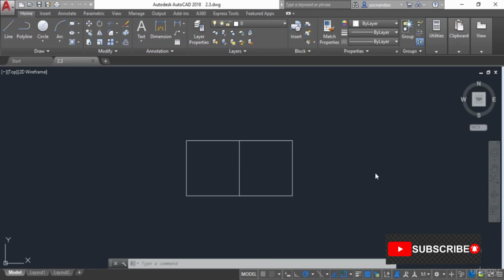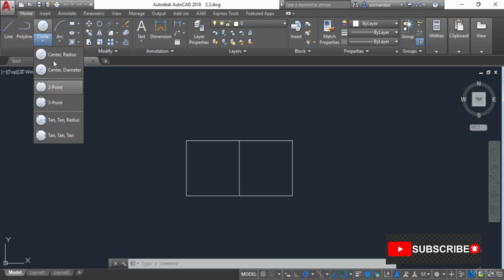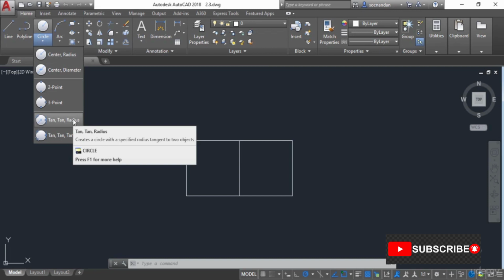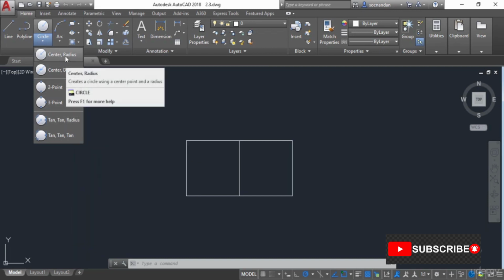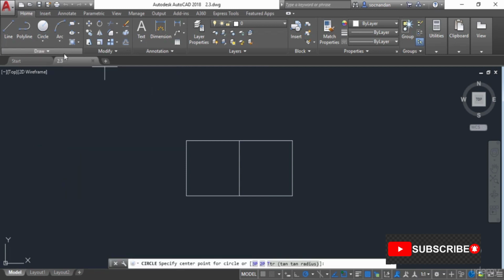In this video, I'll tell you about the circle command of AutoCAD. So you'll find the circle tool here on the Draw panel of the Home tab, and when you click on this small arrow, you'll see the circle flyout with 6 different methods of making the circle. The most basic method of making a circle is the center radius. Now in order to select the command, you can click on this center radius option, or you can also use its command equivalent, circle or C.